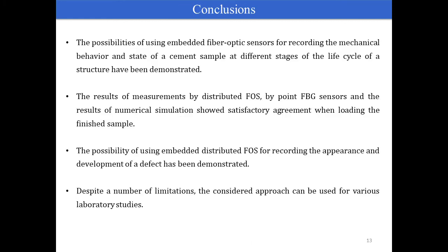Conclusions. The possibility of using embedded FOSs for recording the mechanical behavior and state of the cement sample at different stages of the life cycle of a structure has been demonstrated. The results of measurement by distributed FOS and by point sensors based on the Bragg gratings and the result of numerical simulation show satisfactory agreement when loading the finished sample. The possibility of using embedded distributed FOS for recording the appearance and development of defects has been demonstrated. Despite a number of limitations, the considered approach can be used for various laboratory studies.